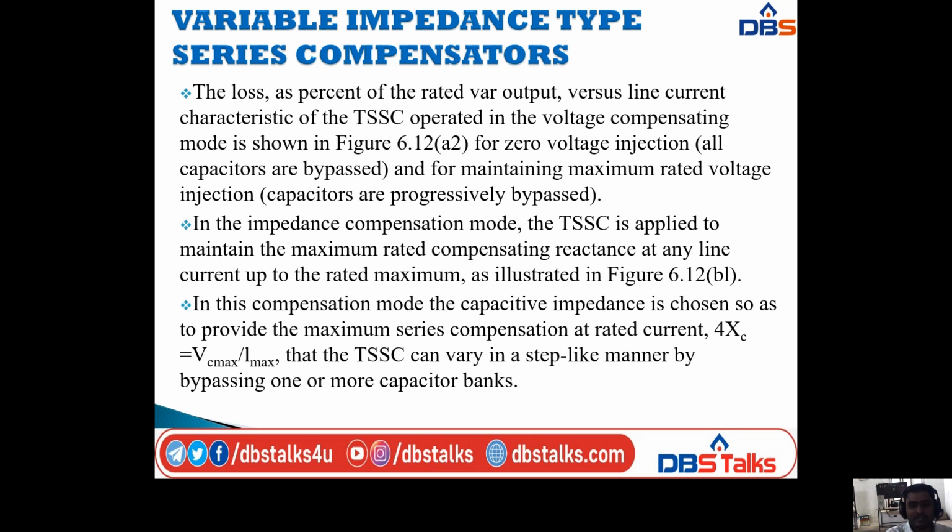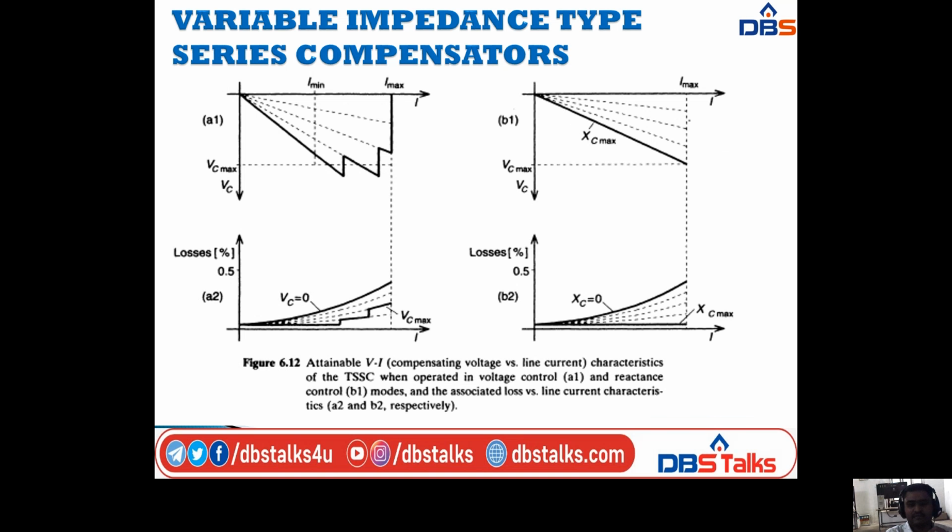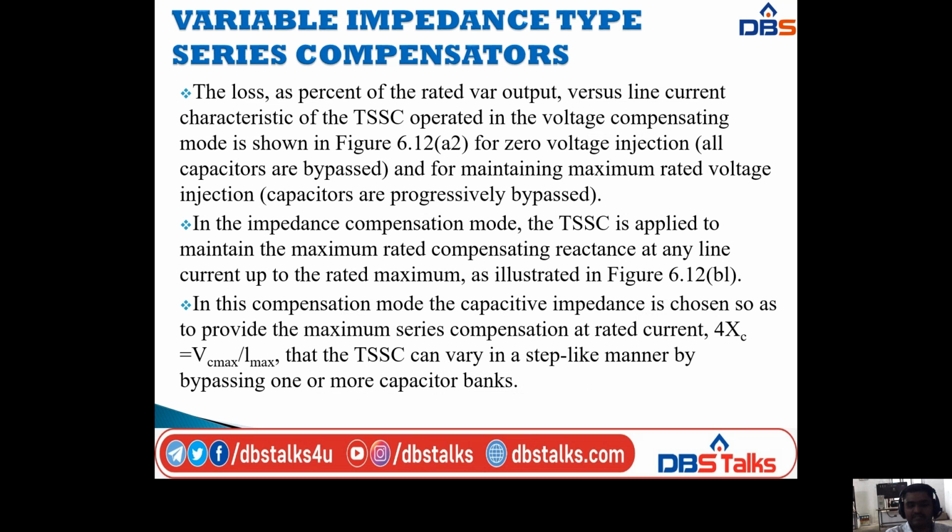In the impedance compensation mode, the TSSC is applied to maintain the maximum rated compensating reactance at any line current up to the rated maximum. That is illustrated in the B1 diagram of this VA characteristic, which is the reactance control. A1 is the voltage control and B1 is the reactance control.